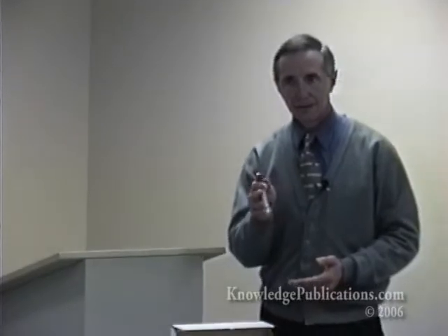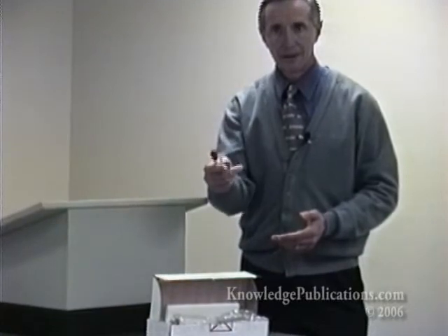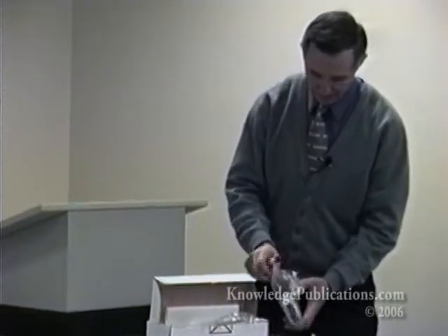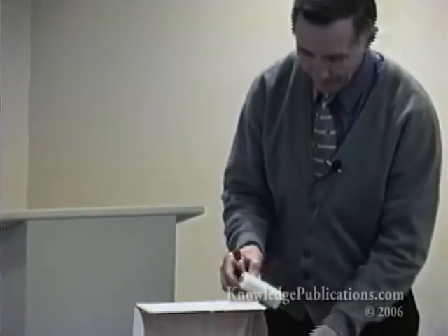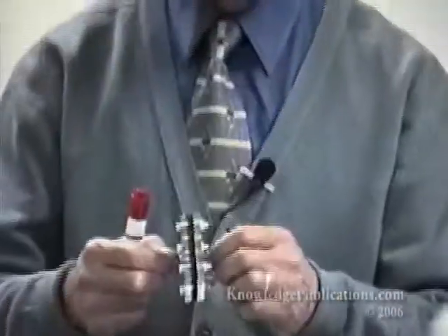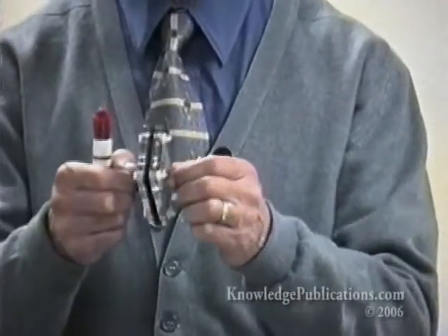Is that fuel cell in the box there a good example of all those forces? It is. This fuel cell that we're going to be putting together is an excellent example of all of these forces. It's built to perform most of these functions without the subsystem of a circulating pump, and can do so because we're going to use such a small area cell that the amount of heat that it can give up to the atmosphere is adequate to keep it from overheating. Even with plastic, it is able to maintain a temperature that's adequate to keep it from overheating.